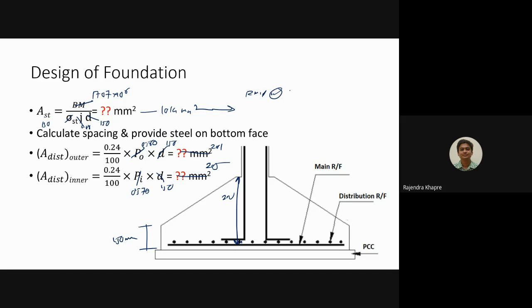110. तो 110 है, so we can go for 100. ठीक है. So the horizontal bars, the one which is shown in solid line at the bottom, has to be provided as 12 mm dia bars at 100 mm center to center. Okay, and the dots are nothing but the distribution reinforcement. So minimum AST is something like 201 and another is 205.